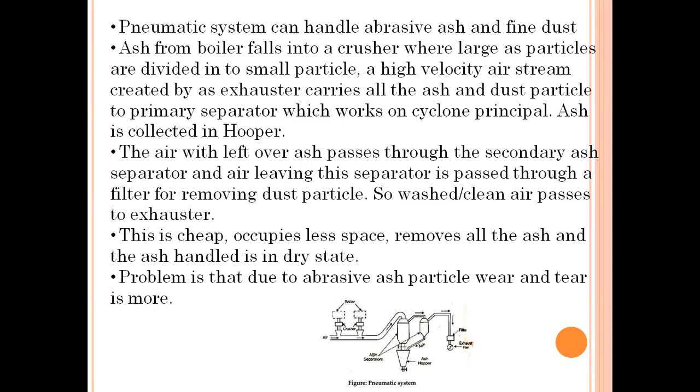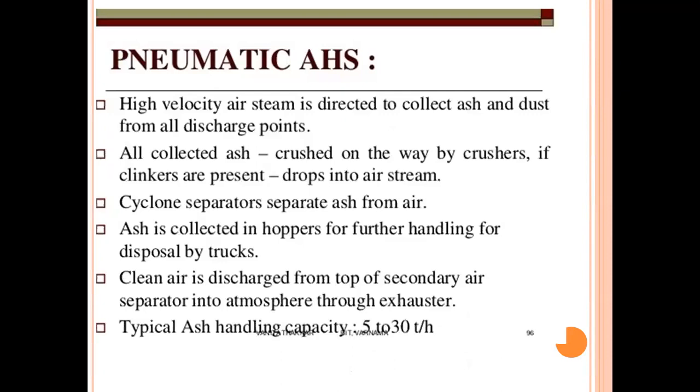This is cheap, occupies less space, removes all the ash, and handles ash in the dry state. The problem is that due to abrasive ash particles, wear and tear is more. Pneumatic ash handling system: a high velocity air stream is directed to collect ash and dust from all discharge points. All cooled ash is crushed on the way by crushers. If clinkers are present, they drop into the airstream.